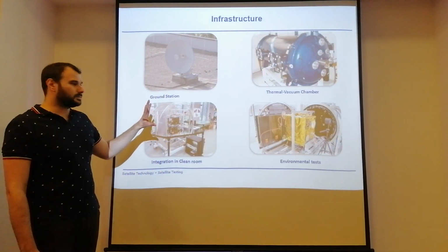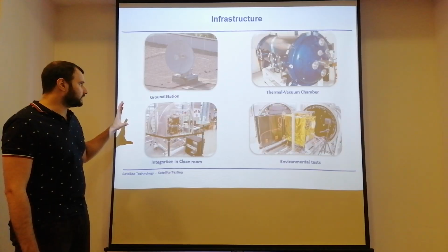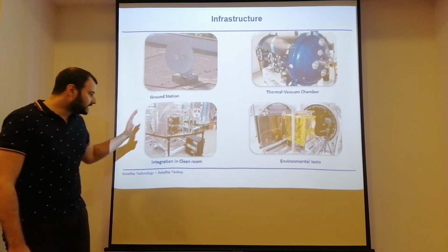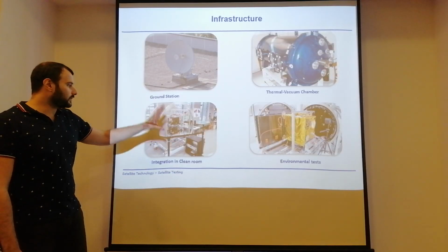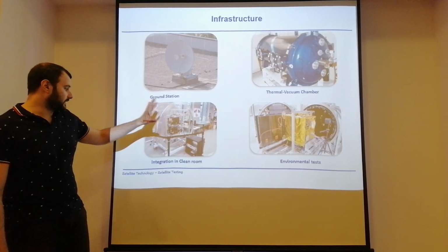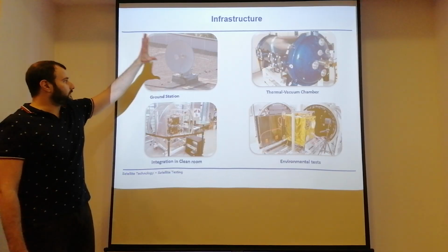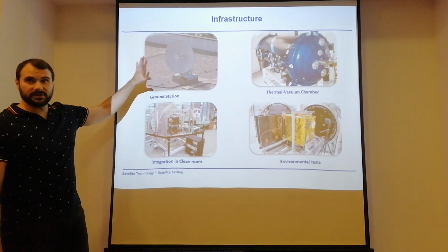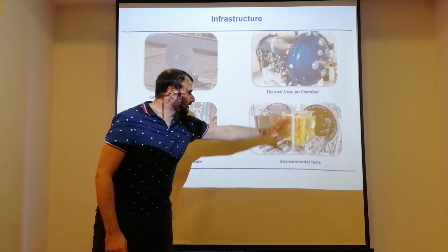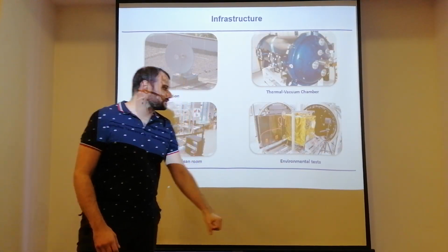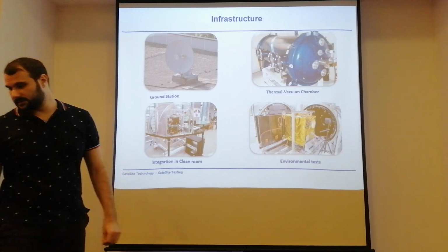Integration, to really assure your cleanliness, should be done in a clean room, in a clean environment. So all the integration, especially of the optics, is done in the clean room. We have a ground station for the compatibility tests and the operations tests. And of course, all the environmental tests need to be done in different environmental simulators.